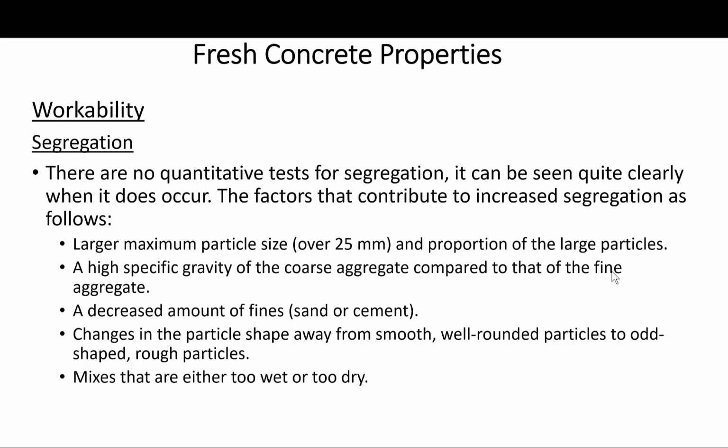The use of finely divided mineral admixtures or entraining agents reduces the tendency towards segregation, but careful handling and placement methods are more important than this factor.